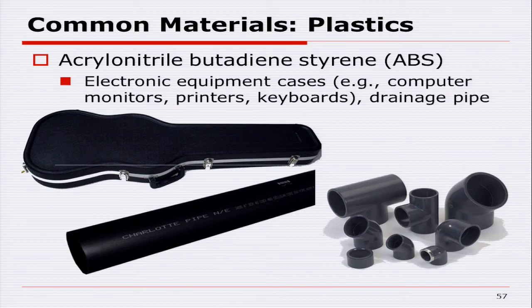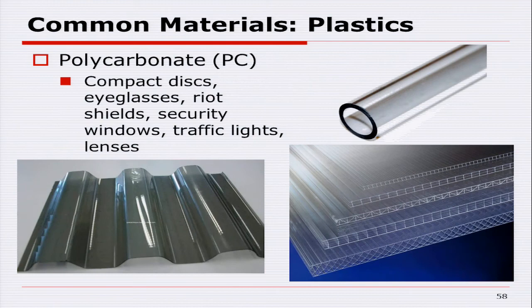They were rotomolded. So what you do is you basically have an outside mold. It's like a clamshell, basically, you bring together, and then you introduce the material into it, and this whole mold is rotated and spun on a couple different axes so that the plastic is forced to the outside of the mold and gives it a uniform thickness, and then you just take the mold off and you have your tank. Those were ABS tanks, and that is how they were manufactured.